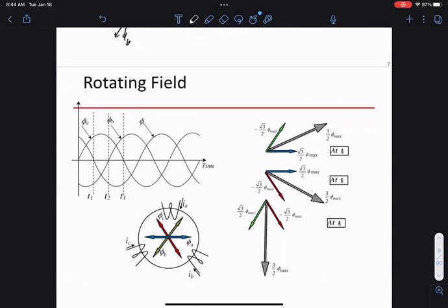Okay, so again, just to recall, because this is 3-phase and all phases are balanced, this rotating field will have constant magnitude and constant frequency. So that's one reason we use 3-phase, right? We do not have a difference when this thing turns. All phases are equal. So once it turns, it will turn at a constant frequency and constant magnitude. Okay, so this will turn at some frequency.